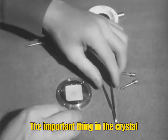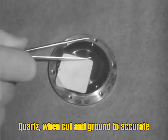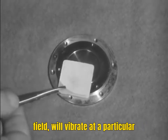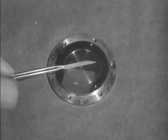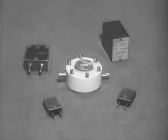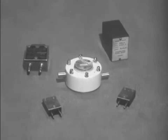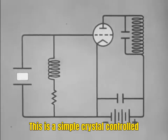The important thing in the crystal-controlled oscillator is quartz. Quartz, when cut and ground to accurate dimensions and placed in an electrical field, will vibrate at a particular frequency determined by its physical dimensions. The mounted crystal for the indicated frequency looks like this. This is a simple crystal-controlled oscillator circuit.